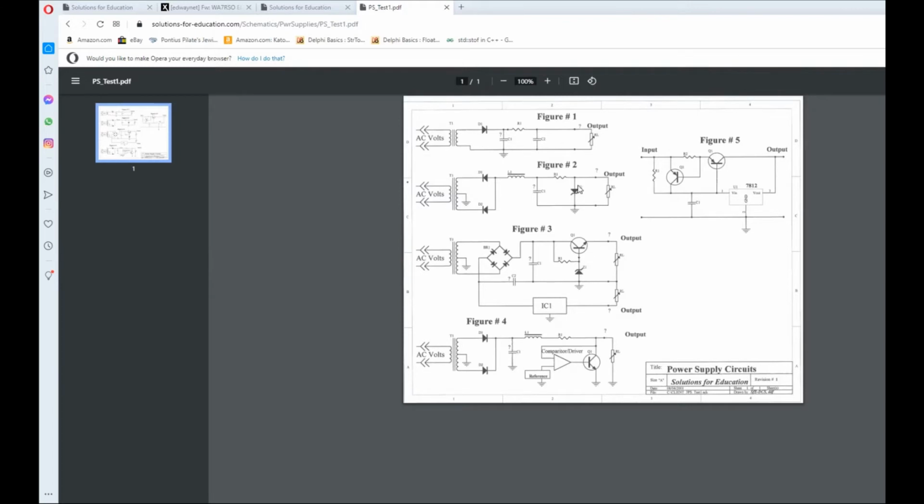You pull the load off of this guy, and that means that this poor Zener diode now has to carry not only the little bit of load it had to begin with to compensate for changes, but now all of the load. And you better have a resistor up here that's properly set to limit the amount of current, or you're going to blow that Zener right out of the picture. So here are advantages and disadvantages of series regulation and shunt regulation.